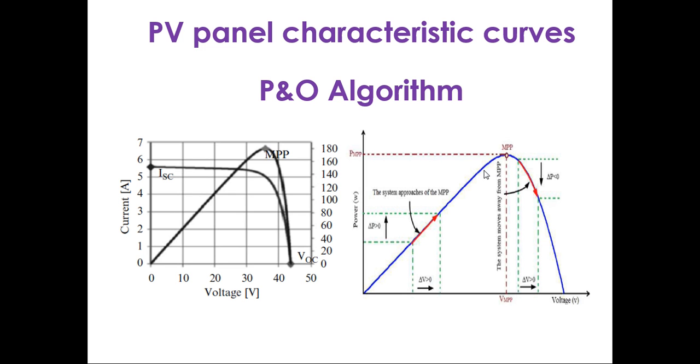To select the perturbation size, if you go with a higher perturbation size, you will reach this point within a short time. Suppose I select from here, this perturbation, this and this might be any digit, but our accuracy is less.